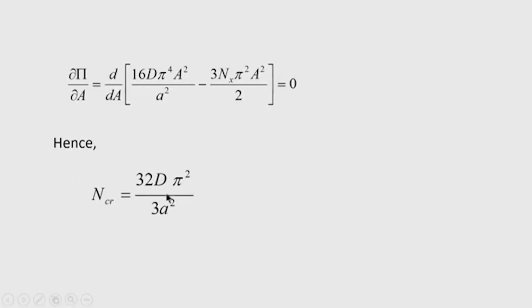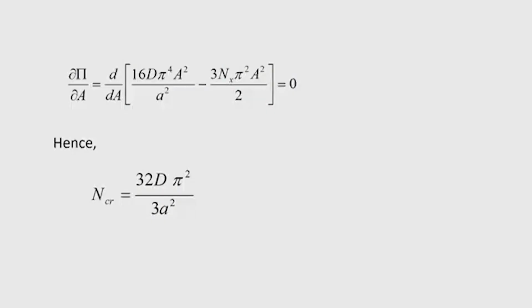So, this is one method by which you can calculate the buckling load of the plate using strain energy, and here we have taken only one term in the series, but if you want to increase the accuracy of the result, then you can take a larger number of terms.